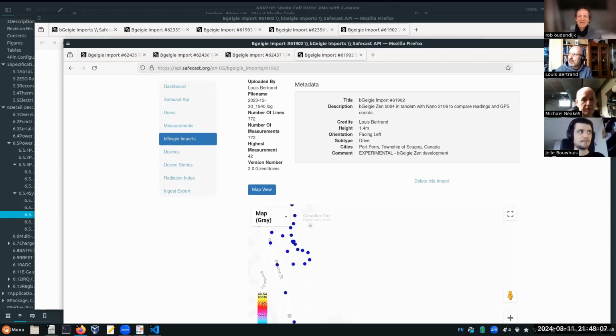The great thing is the current for charging is 500 milliamp, and that's good. That's what I really like. It's got a very beefy 4056. Apparently, according to the data sheet, it'll go up to 1 amp. The 4056 goes to 1 amp, but 500 is fine.